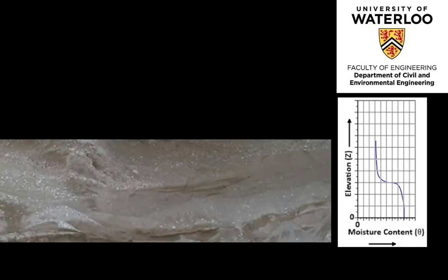We begin the procedure for the estimation of water infiltration into soils and their underlying porous media with a definition sketch of a soil moisture curve, which is unique to each soil and underlying porous media type, characteristics, and geological setting. Theta S defines the fully saturated soil condition at a given depth, which is defined at an elevation of 0 meters, which is coincident with the water table elevation.